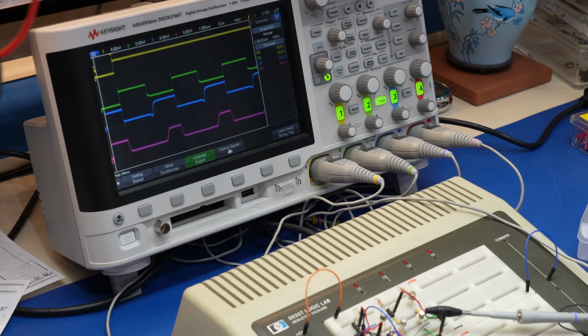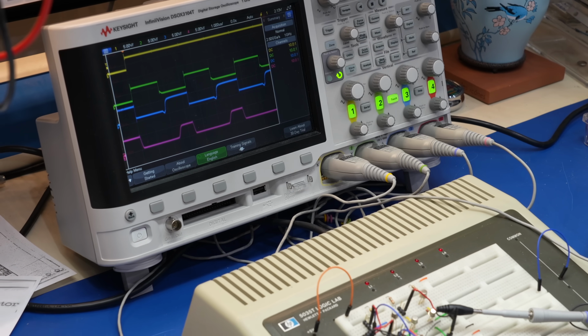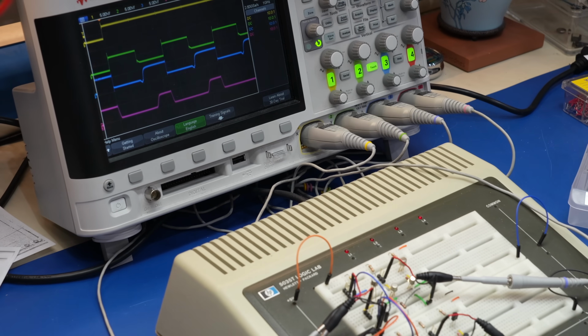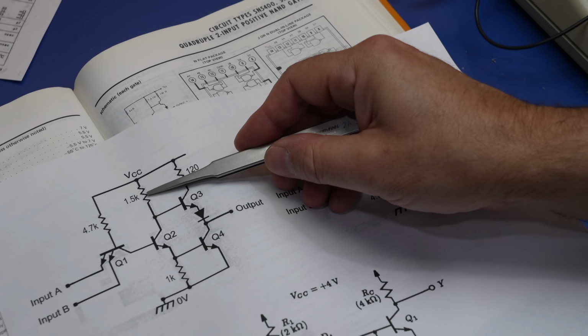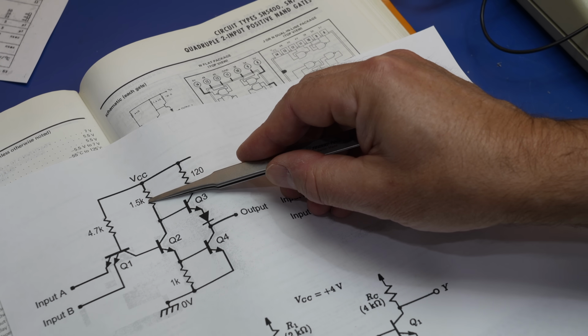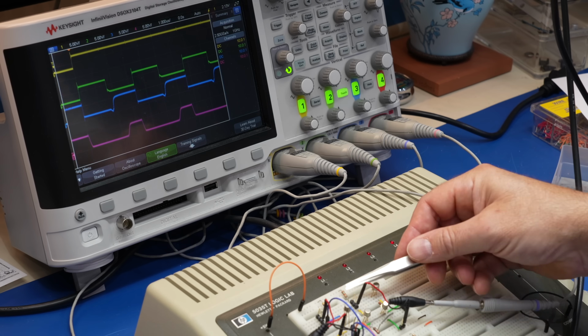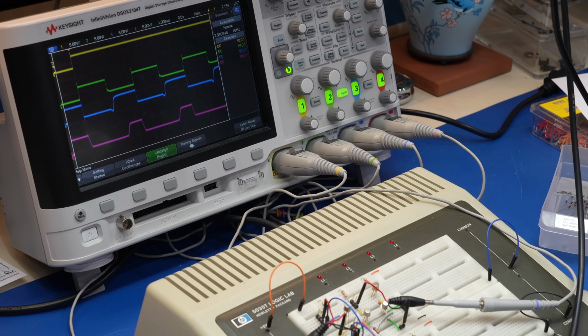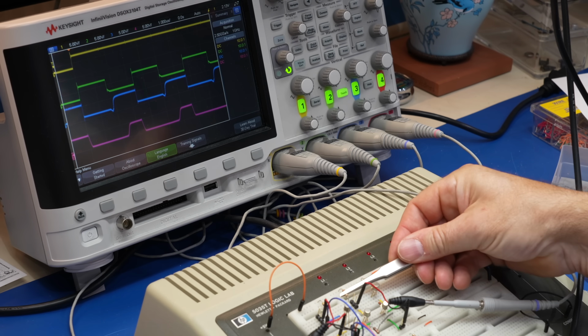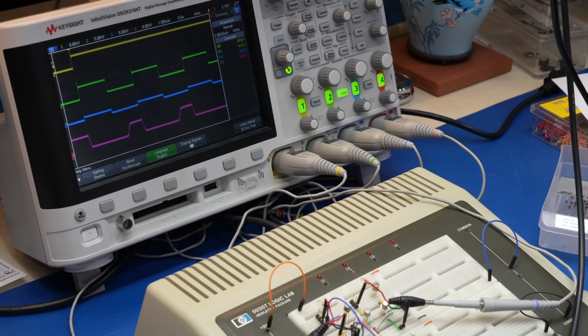When I was studying the circuit, that slow transition caught my eye right away, and that is symptomatic of a transistor where there is some capacitance somewhere and it cannot be discharged fast enough. There is a usual trick for that, which is to put more current into the circuit and lower your resistors. So I'm going to do just that, take this resistor and lower it to 470 ohms. When in doubt, make your circuit faster: you drive it harder, you put more current through it, and it will get faster at the expense of power consumption.